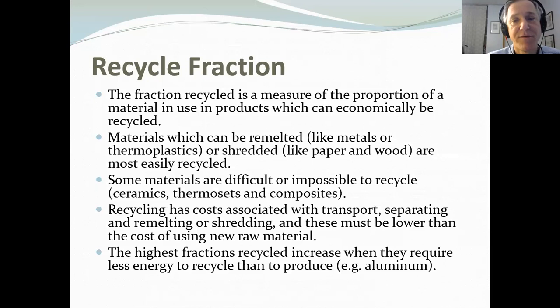If you have all these beautiful brass screws in your design, at the end of its life, can those beautiful brass screws be extracted? Well, probably not. They're probably just going to get thrown away. But if you have some feature where all the fastening hardware is in one little spot and it can be easily removed, that's a good goal in terms of sustainable design. And economically, it's an attraction as well, especially for valuable metals. Valuable metals, like aluminum and copper, are often recycled where steel is not, because steel isn't worth that much. So it does affect designers, and we'll look at that a little bit more in just a moment.